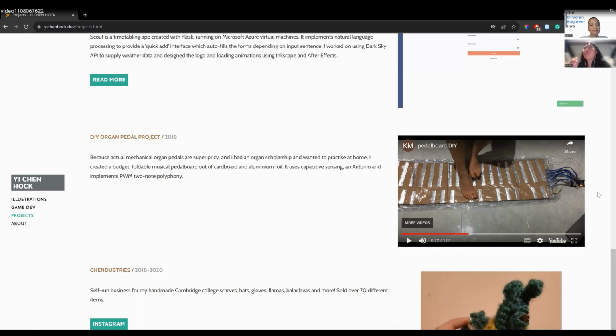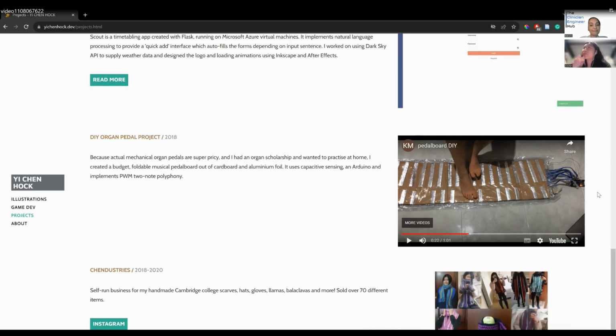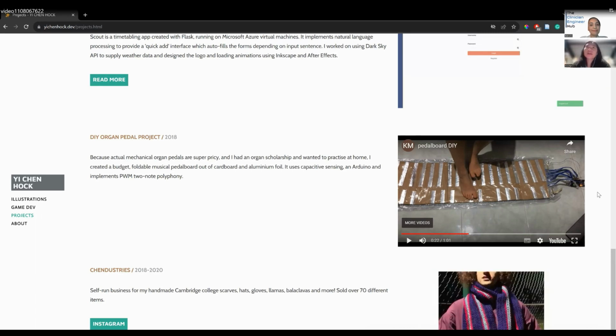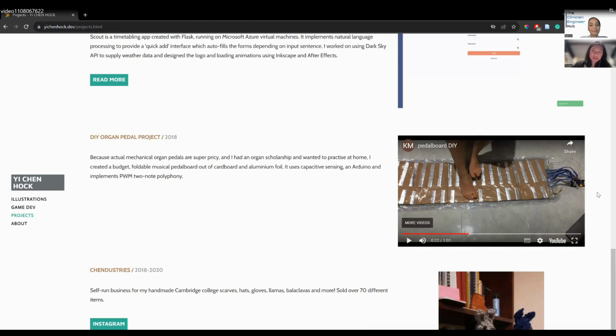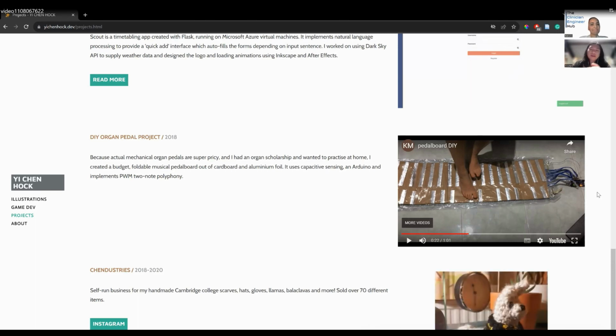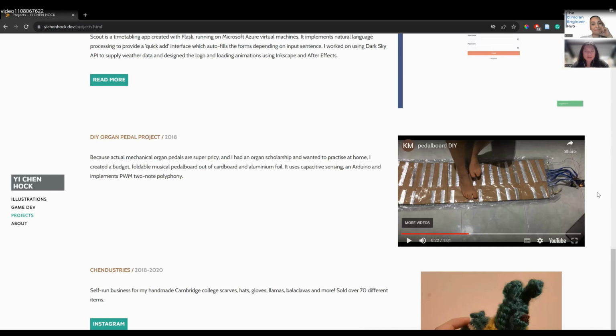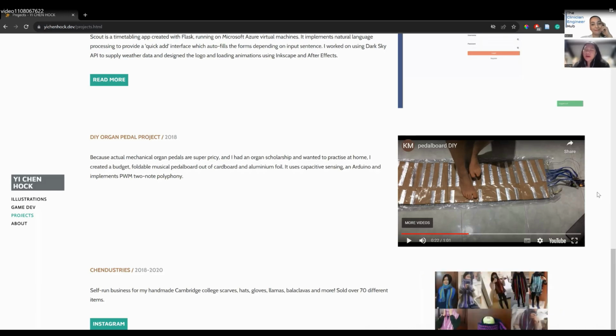basically, you can pass a square wave through it, and then you can see it charge and discharge. And then with that, you can see at what time it reaches half, and you can calculate the time constant, which you can use to calculate the capacitance and see that it's changing. So with that, I was able to do that. But because of all the interference, that was a really challenging problem. I had to experiment with different thicknesses of the cardboard.